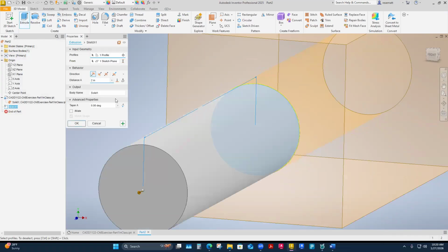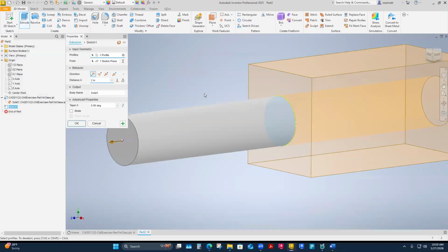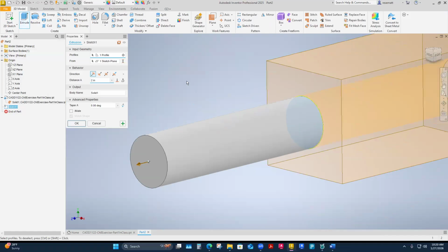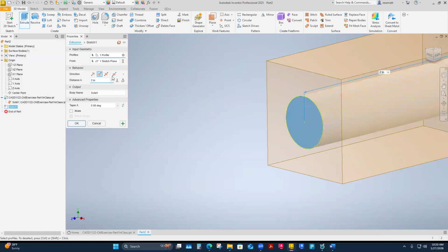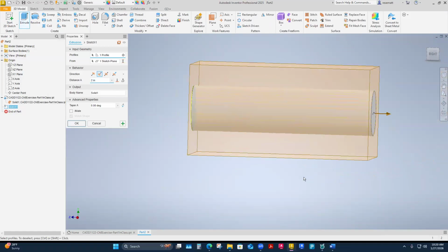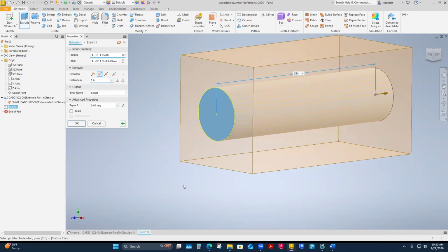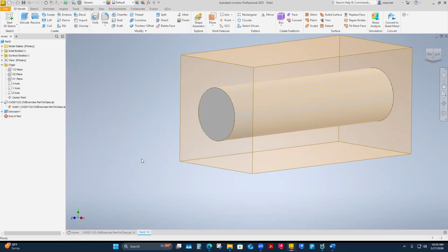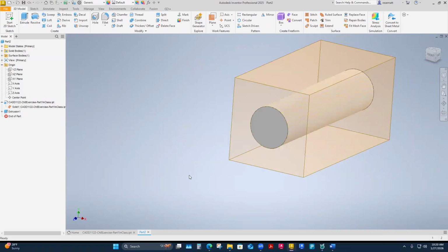And then I extruded that because it's just a projected geometry. It's not like a new sketch, I'm actually just working from that derived part. I said to go this way, so it's in the hole there like that. And then I said okay, I entered 2 inches. And your little part always lives in that other part.